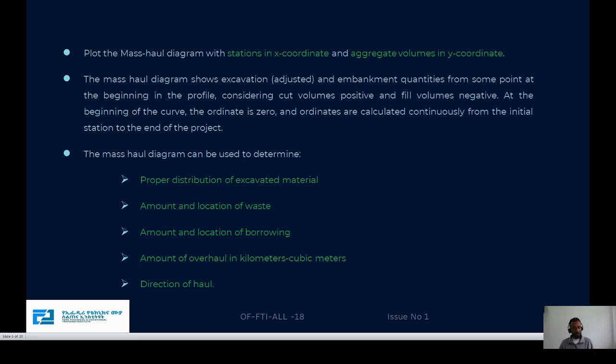To plot mass haul diagrams, the x coordinate is the stations, the distance, and the aggregated volume is placed on the y coordinate.